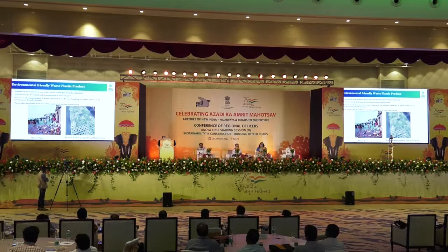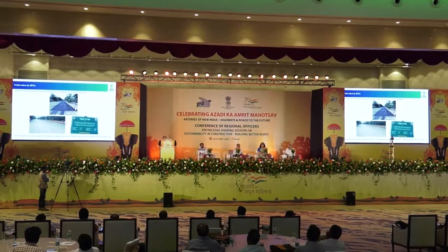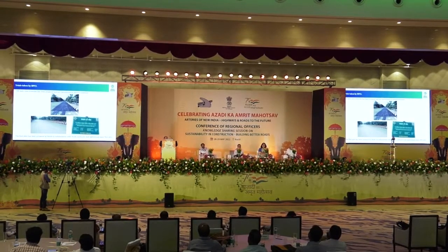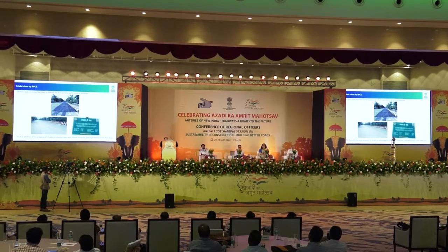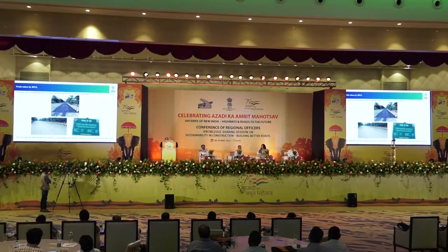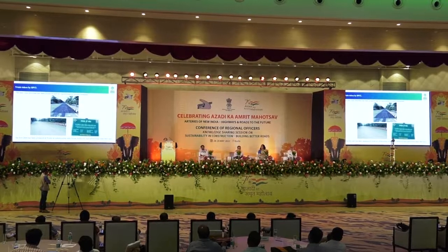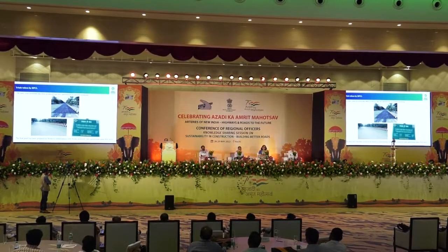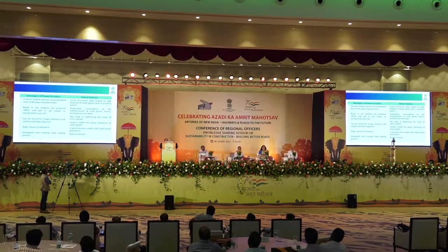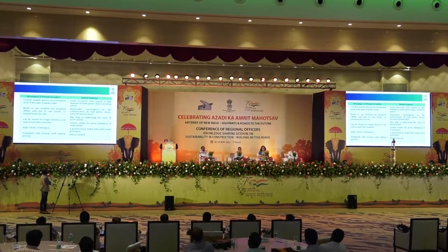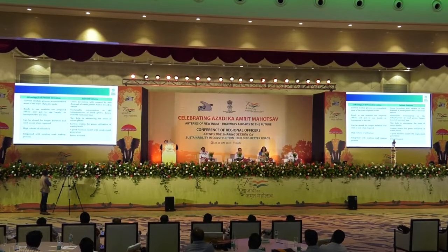So by using this particular method, 1 kilometer of road with 8 meters of width consumes almost 50 metric tons of plastic, which is actually very high quantity of waste plastic we are able to utilize by using this particular way. Till now we have spread 9 stretches, and with the help of Noida Authority we have laid one pilot road in Noida also, and it is functional from November 21. Salient feature of this particular product is that these are the modules which can accommodate most of the types of waste plastic, and they are ready to use.